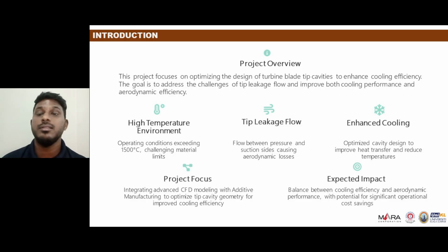Specifically, the tip cavity manages the tip leakage flow, the air that leaks from the high pressure side to the low pressure side over the blade tip. This leakage creates a vortex, leading to aerodynamic losses and elevated temperatures, which negatively affect engine efficiency and blade durability. Optimizing the tip cavity design is therefore key to minimizing leakage and enhancing cooling. However, this is a complex challenge due to turbulent flow, heat transfer interaction, and competing requirements for aerodynamic efficiency and thermal protection.